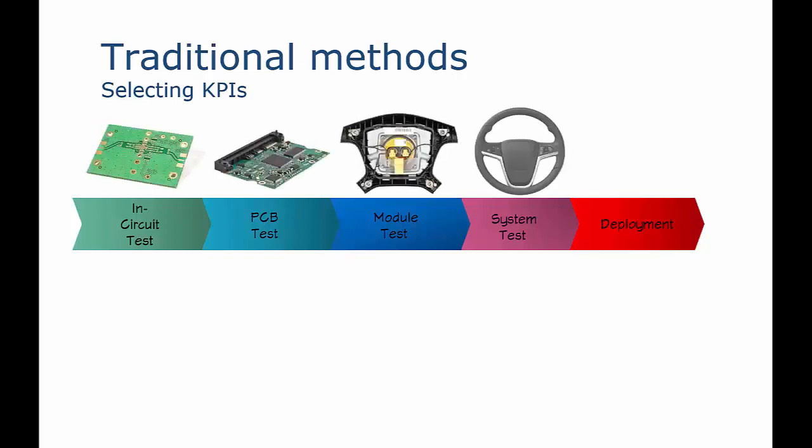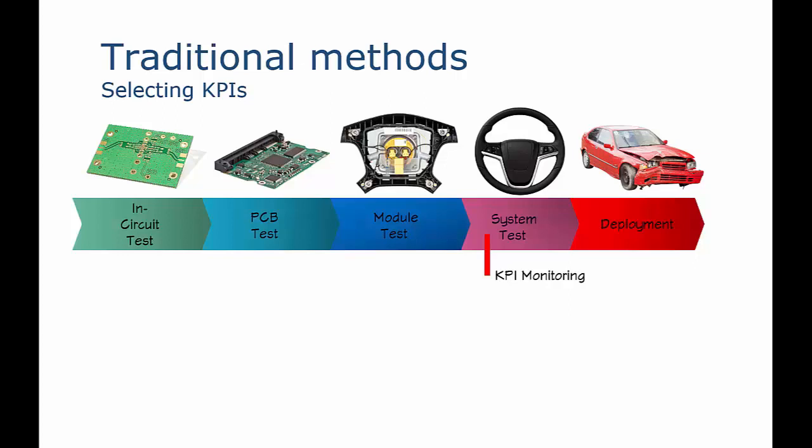Very often, these are well downstream in your manufacturing process, like at system-level testing. The origin of a failure, however, could just as easily be located upstream of where the KPIs are recorded. So a poor batch of PCBs that was allowed to pass all of a sudden means that you need to move the full system to repair and deconstruction, as opposed to just fixing the PCB.